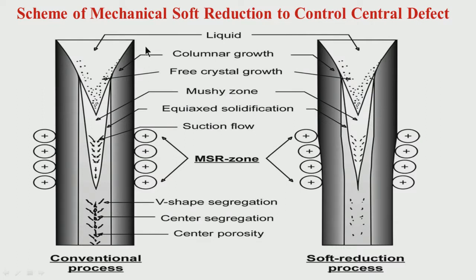Here the thickness is maintained by these rolls; the distance between the rolls will give you the final dimension. Now, if you can create some amount of squeezing, that means generate some mechanical pressure in the final area where solidification is taking place, this is very important where you give the pressure.